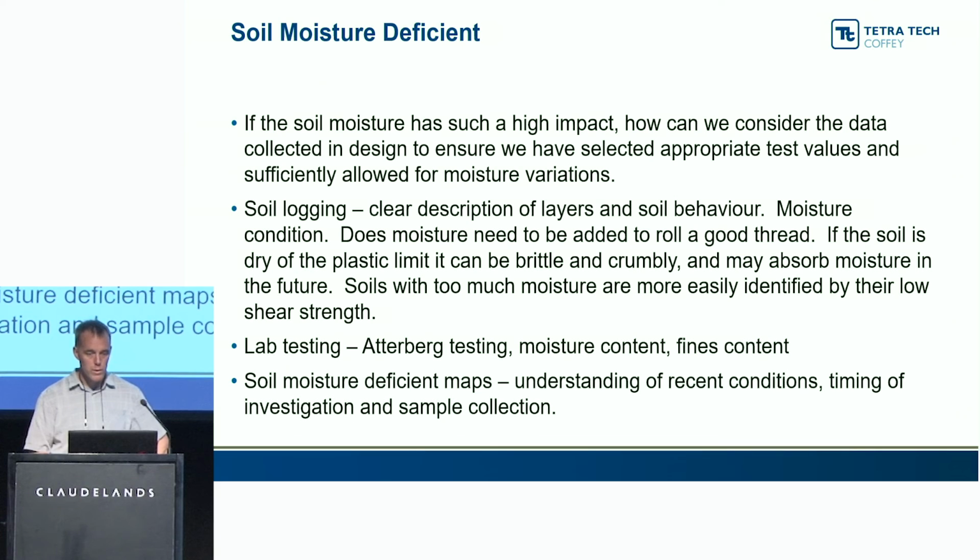Moisture content's important. If you're getting logs from a geotech and it's showing dry, dry, dry all the way down to 2 metres, it should be ringing alarm bells that the scala results and shear vanes might be wrong.